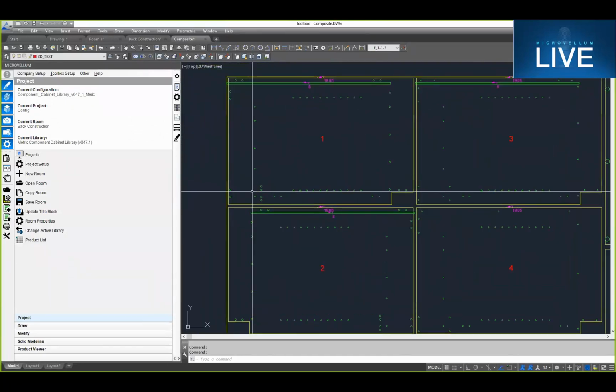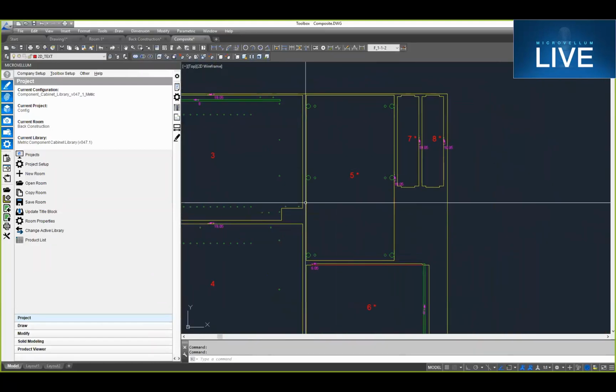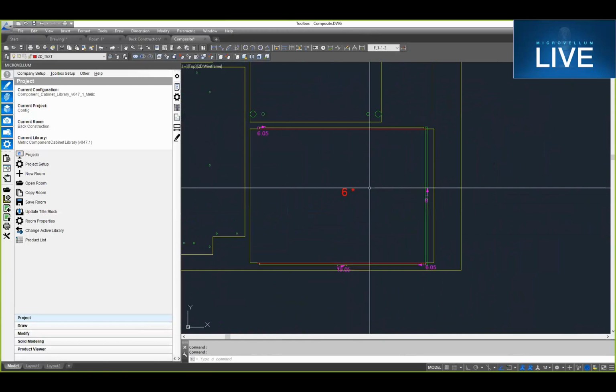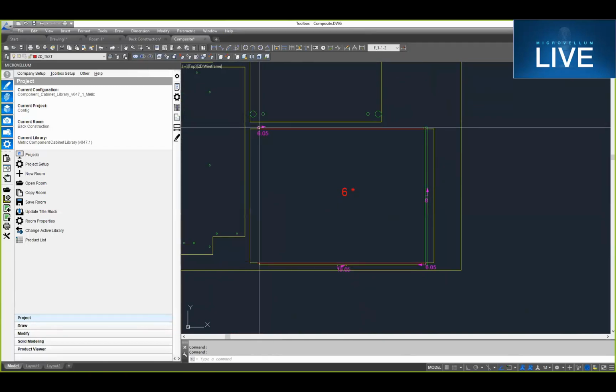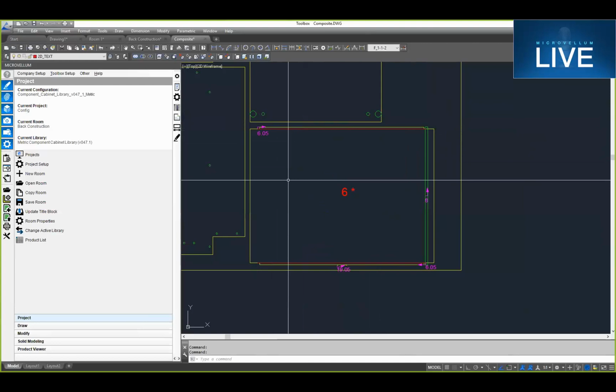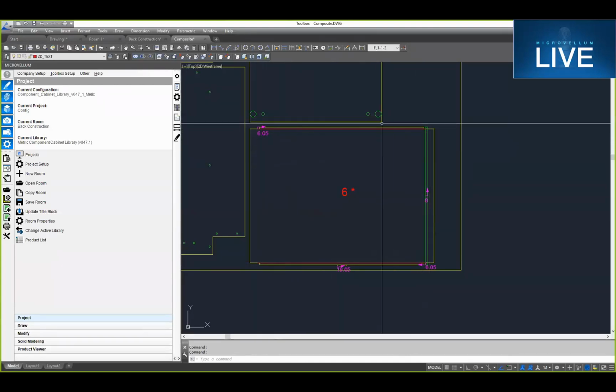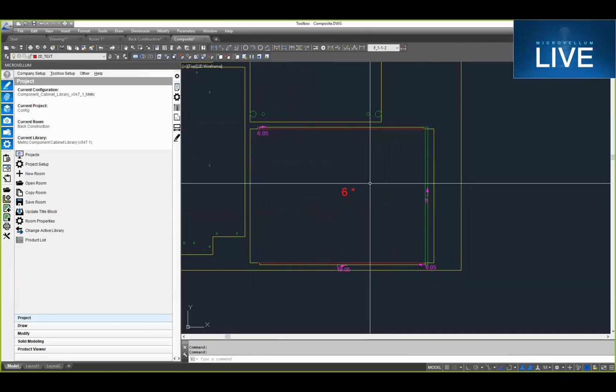Here I've got some dowel manufacturing, I've got some cam manufacturing going on here. This is a Dado construction. So here you can see I've got machining going along to cut this tenon down, cutting 6 millimeters off of it down to our finished thickness to control that for our Dado. You can see it's a red line, so it is a flip operation.